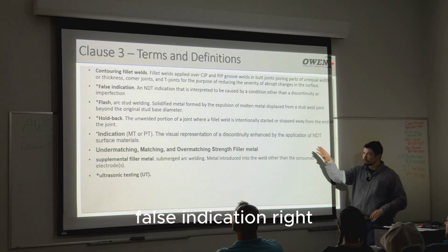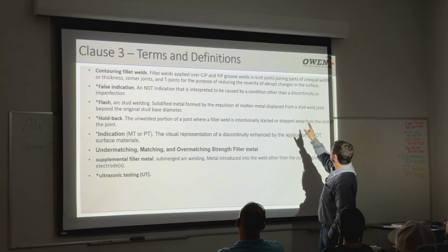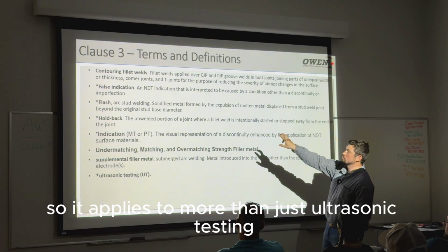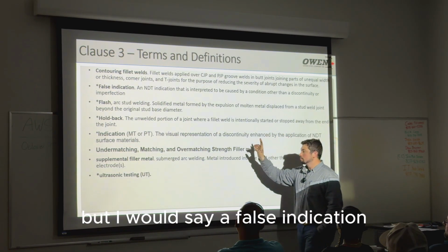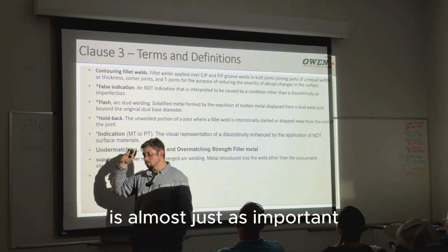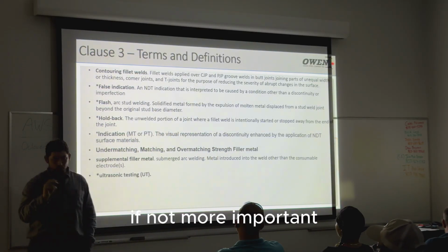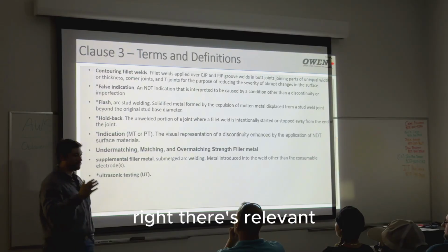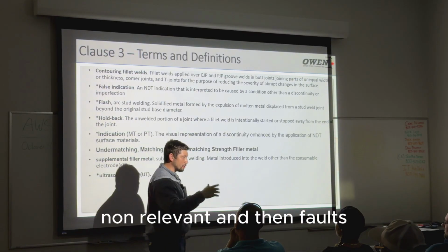False indication, right? Notice how it doesn't have UT following it, so it applies to more than just ultrasonic testing. But I would say a false indication is almost just as important, if not more important, than a non-relevant indication or a relevant indication, right? There's relevant, non-relevant, and then false.